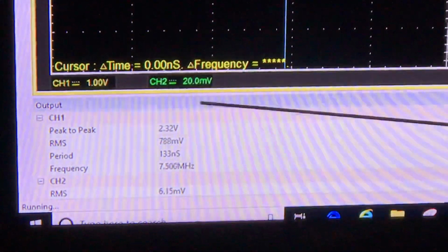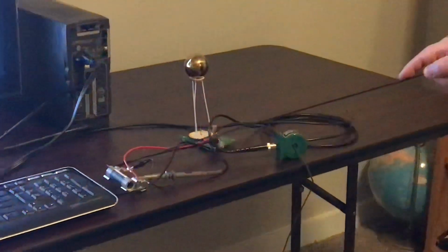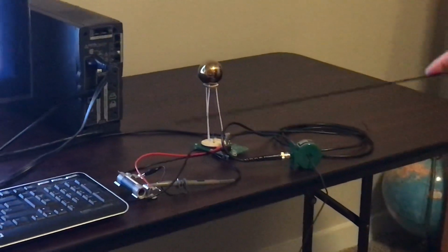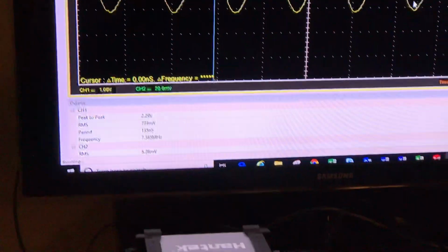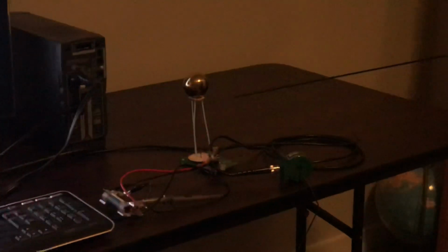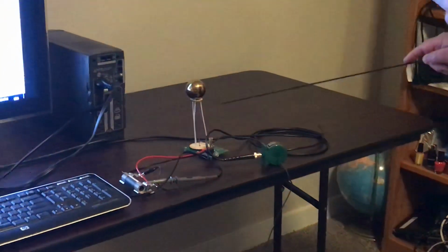Over here at the receiver, the voltage across this 1000 ohm resistor corresponds to 1 milliamp according to the measurement you see here. Remember that this receiver has no onboard power supply. All of its energy is coming from that transmitter.